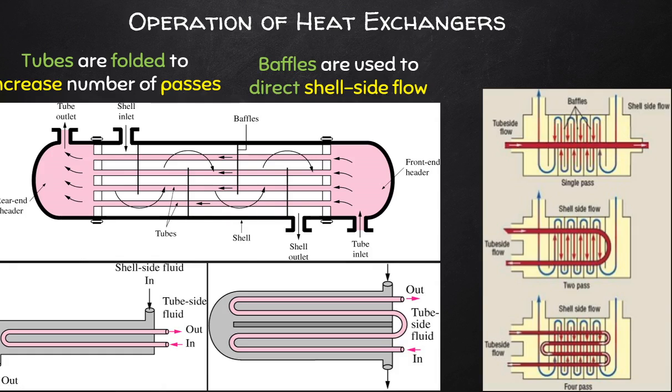Now, the design of heat exchangers goes hand in hand with their application and how transfer is optimized by such designs. In the design of a shell and tube heat exchanger, for example, flow enters and leaves the piping through what are known as headers, and the pipe midsections are supported by baffles. The baffles have a second usefulness in that they help to guide the shell side fluid over the pipes in a cross-flow type manner, as shown in the top left diagram.